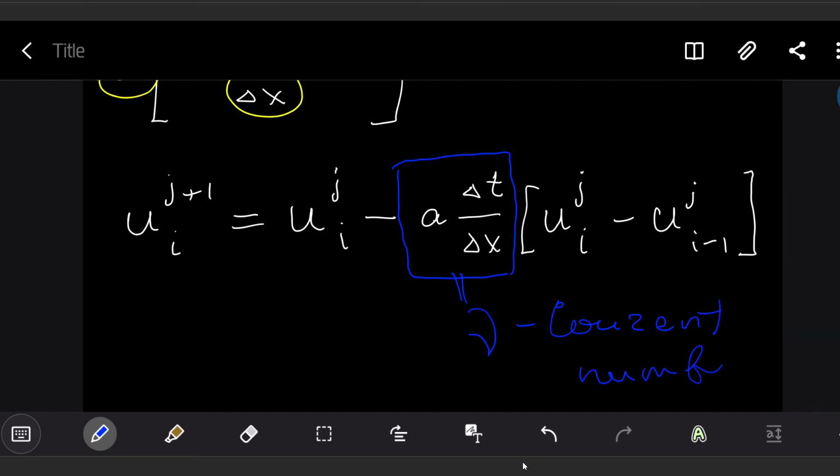It's a dimensionless criterion which gives us the relation between the velocity of the flow, or velocity of the process change, proportional to the time step of integration of our equations of the flow and inversely proportional to the step of space integration of the flow equations.